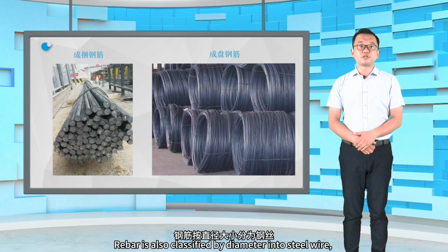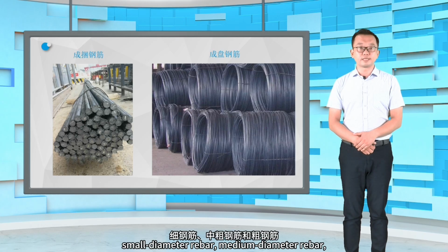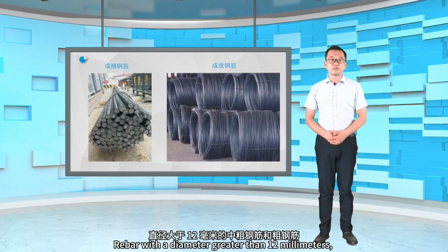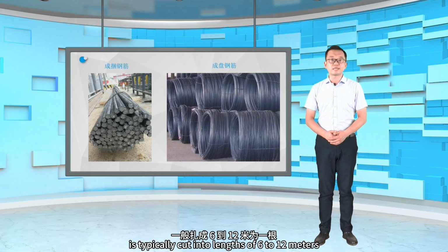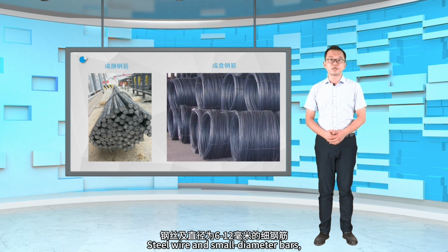Rebar is also classified by diameter into steel wire, small diameter rebar, medium diameter rebar, and large diameter rebar. Steel wire includes cold-drawn wire, carbon steel wire, and indented wire. Rebar with a diameter greater than 12 mm, classified as medium or large diameter rebar, is typically cut into lengths of 6 to 12 meters and delivered in bundles. Steel wire and small diameter bars, 6 to 12 mm in diameter, are usually delivered in coils.